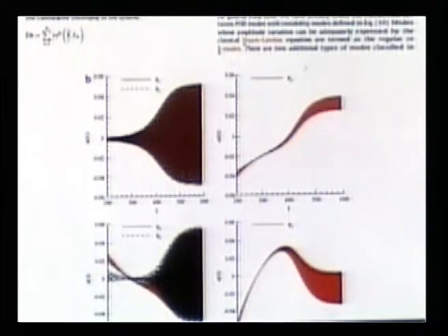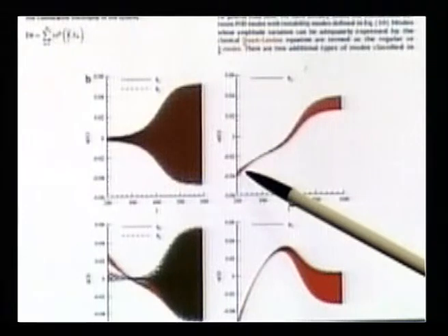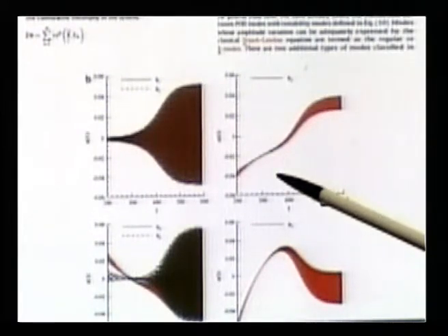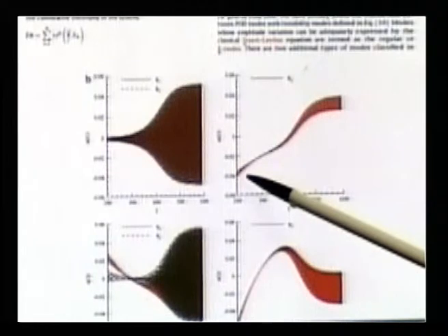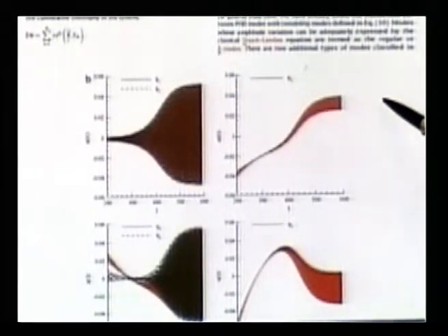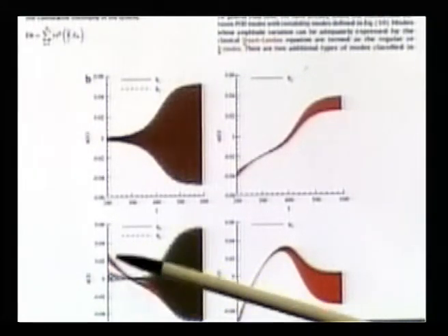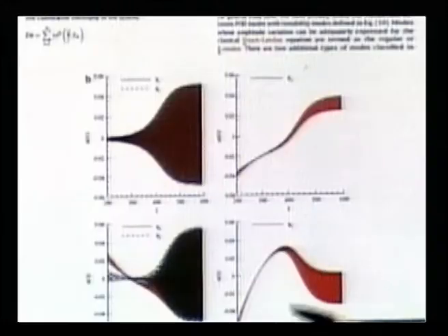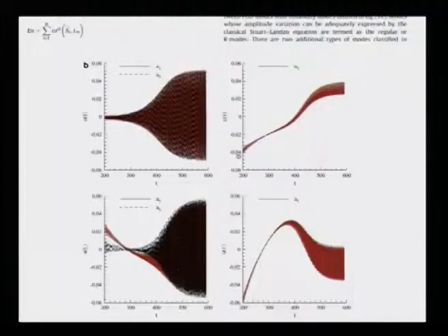And we have the third mode here, which was that shift mode we talked about, which appears singly, and you can see that it does not start off from 0 like flow past a cylinder, because of the strong transient nature of the flow to begin with. So, it starts off with some value, but it does go and settle down eventually there, and this is another regular mode pair. You can see that during the transient state they do not have the pure orthogonality that you expect from POD modes. POD modes are supposed to be orthogonal, but they do not remain so. So, it is very, very instructive for one to understand what is going on here.